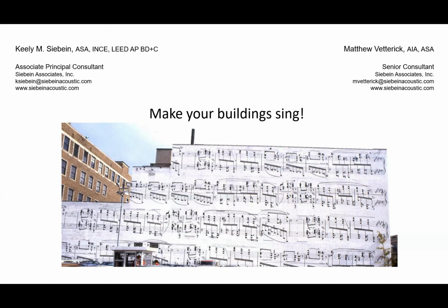Silencers and return ducts are very important, but how loud that unit itself is going to be plays the biggest role. There are ways, if you do have a long enough duct path, or things like the acoustical flex duct for the diffusers, lined duct.